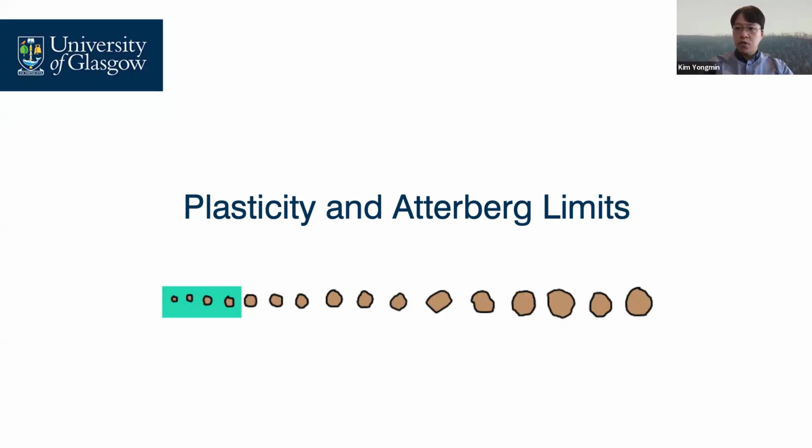Okay, let's move on to the next topic. Let's estimate the plasticities by using Atterberg limits, mostly done for fine-grained soils. So in week 3, we are going to conduct laboratory tests, say simple soil identifications. You touch it and smell it, and then you can feel it with your fingers, and Atterberg limit tests. Don't miss out.